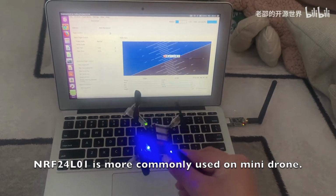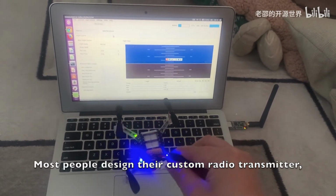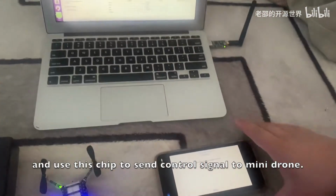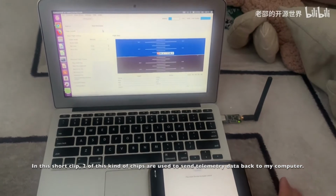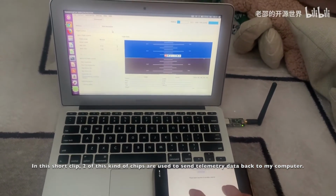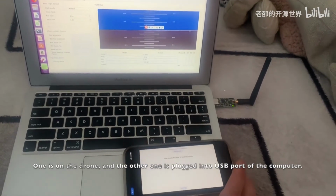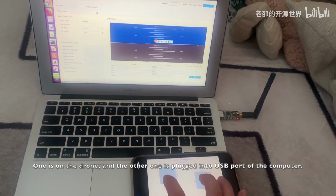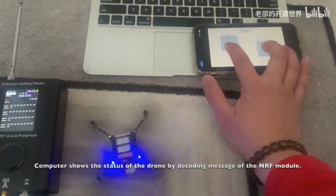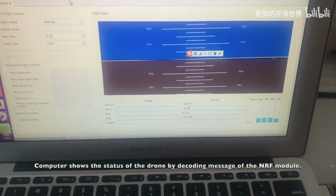NRF24L01 is more commonly used on mini drone. Most people design their custom radio transmitter and use this chip to send control signal to mini drone. In this short clip, two of these kind of chips are used to send telemetry data back to my computer. One is on the drone and the other one is plugged into USB port of the computer. Computer shows the status of the drone by decoding message of the NRF module.